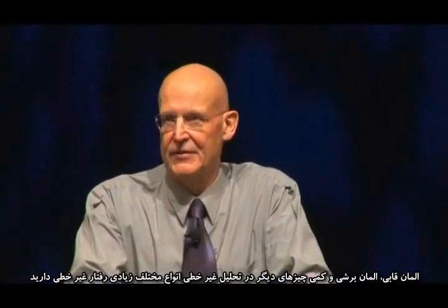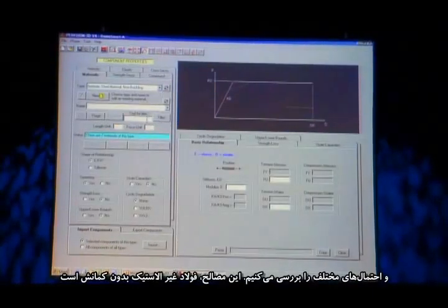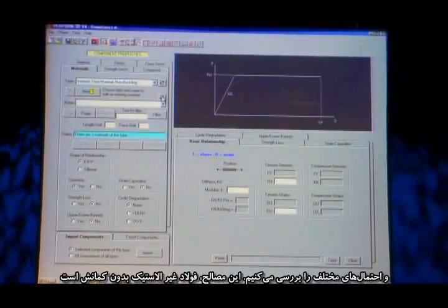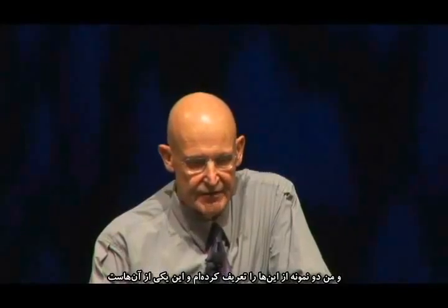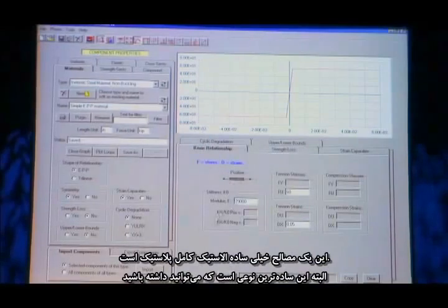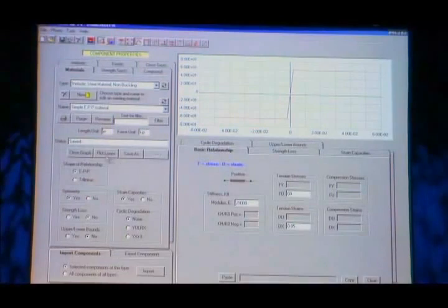Nonlinear, though, you have lots of different types of nonlinear behavior, and you find you need a much wider choice of components. What I'm going to do is go to materials here and just look at some possibilities. This is an inelastic steel material without any buckling. I've set up 2 of these things. This is one of them. This is a very simple, elastic, perfectly plastic material. But this is as simple as you can get.